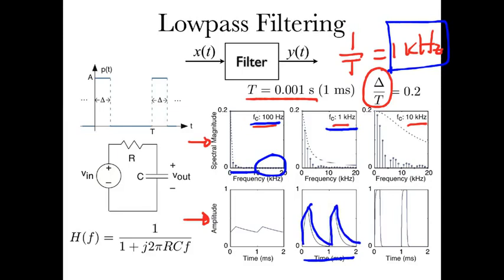And then when the cutoff frequency of the filter is well above the first harmonic, well above the 8th, 9th harmonic, it's way up there, what you see is that the output very closely resembles the original pulse. If you look very carefully, you can see that it has rounded edges, both at the tops and at the bottoms.